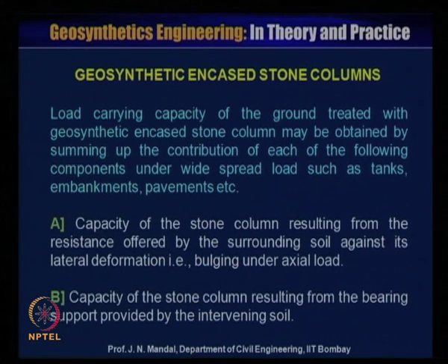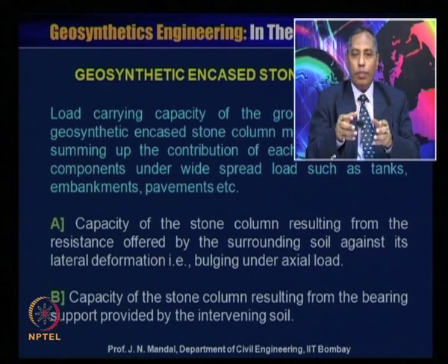Now, the load carrying capacity of the ground treated with geosynthetic encased stone column may be obtained by summing up the contribution of each of the following components under widespread load such as tank, embankment and pavement, etc. A. Capacity of the stone column resulting from the resistance offered by the surrounding soil against its lateral deformation, that is bulging under axial load.